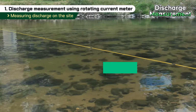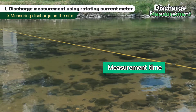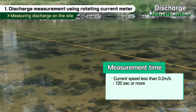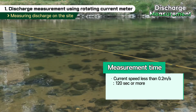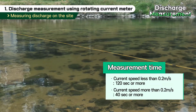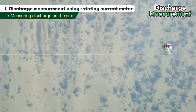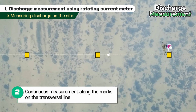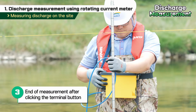The discharge measurement using the rotating current meter has different measurement times depending on the current speed. If the current speed is less than 0.2 meters per second, it should be measured for more than 120 seconds. And if it is more than 0.2 meters per second, it should be measured for more than 40 seconds. The on-site worker records data continuously, following the marks at regular distances on the transversal line. When the measurements are finished, the final step is to click the user terminal button.